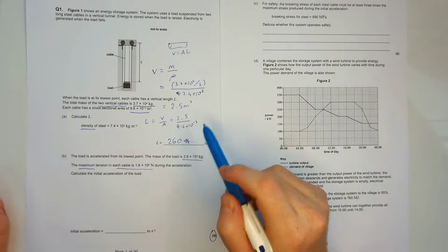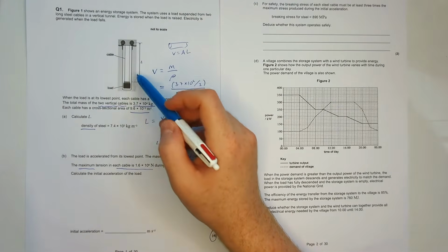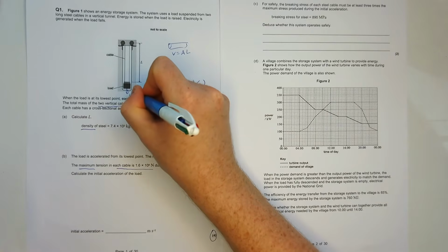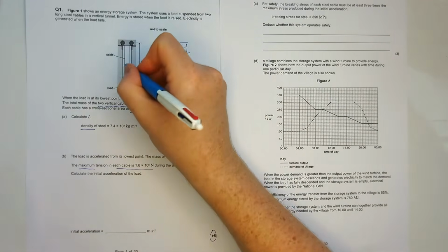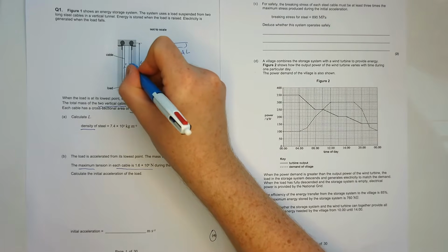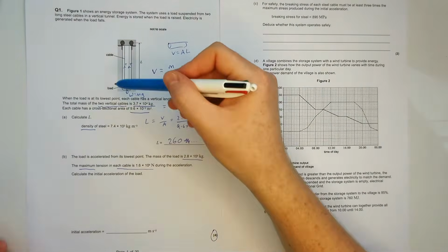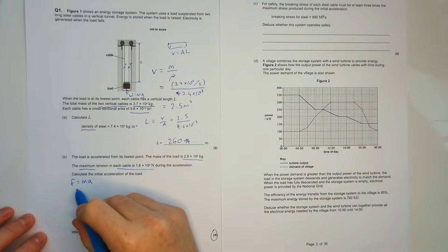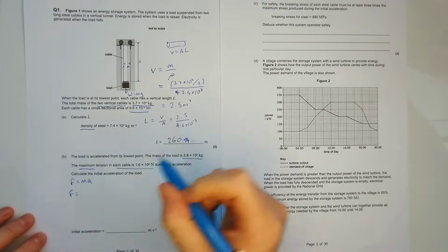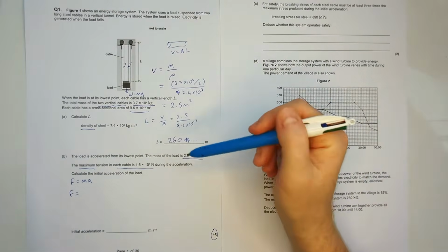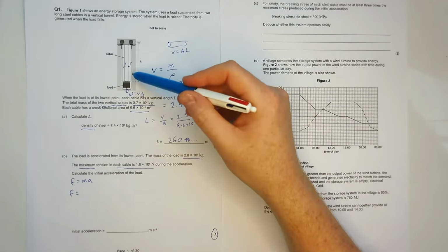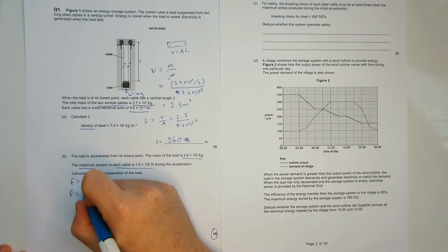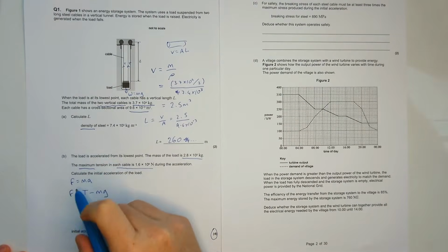So to imagine what's going on here, we've got the cables down here, we've got the load here. We know the load's got a weight, and we've got the weight of the cables. So obviously weight equals mg. And we also know tension of the cable is going to act upwards. So we've got T from that cable and T from that cable. So we're going to have to resolve those two forces and then equate them to F equals ma. Because it's accelerating upwards, as it says it's at its lowest point and it's accelerating back upwards, we can resolve these forces as T minus mg, or T minus the weight. So that's our resultant force.